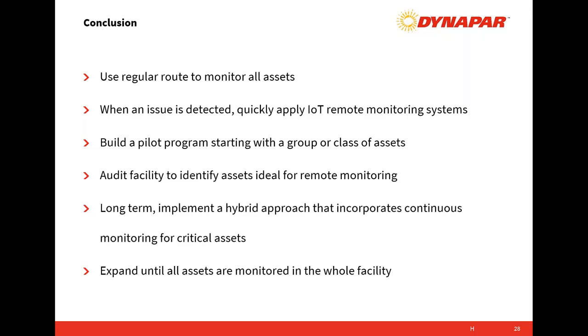On top of that, the unit has the ability to do remote triggering. So basically you set a threshold and say, if the vibration data, either an RMS or peak or even a specific speed is hit, I want the unit to take data.